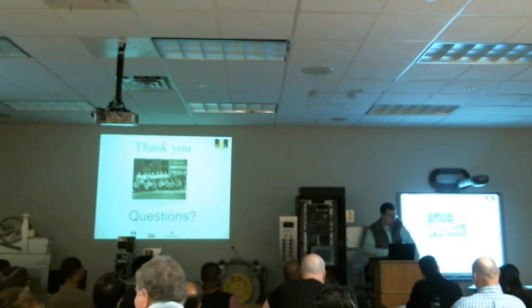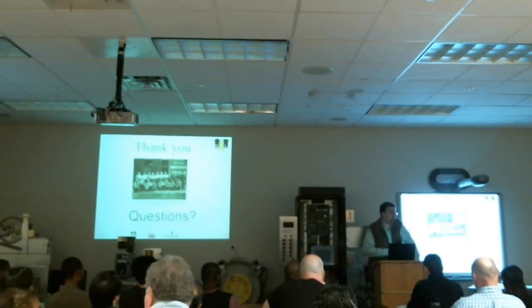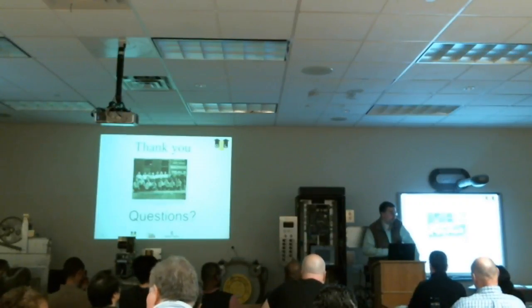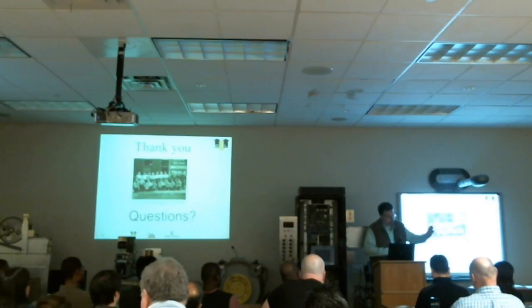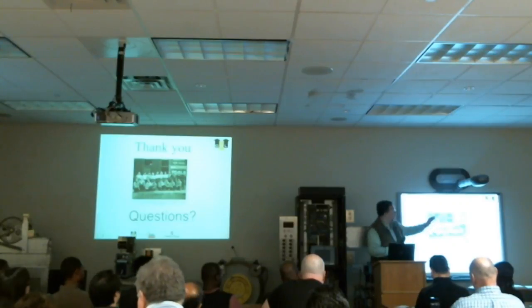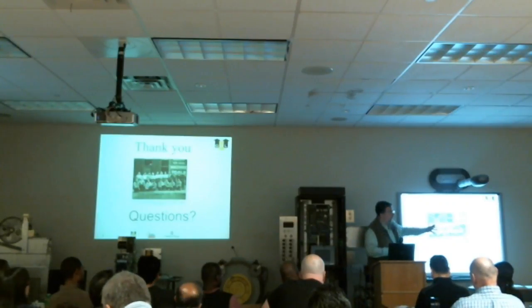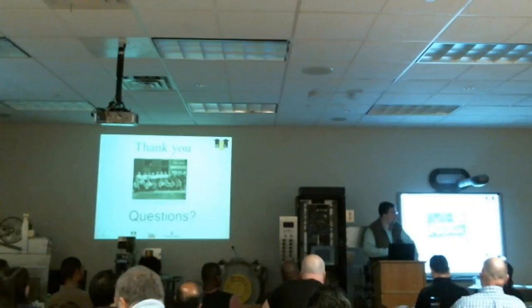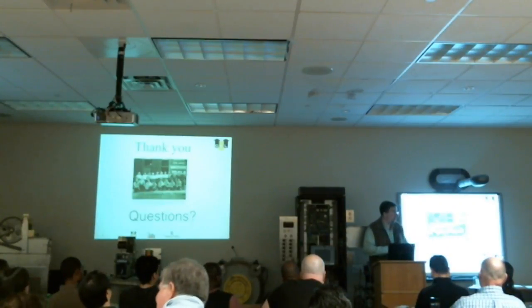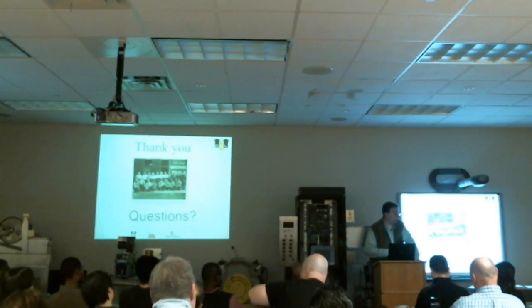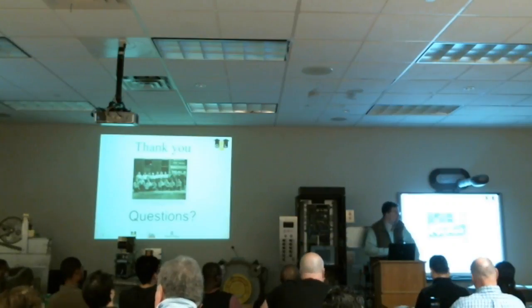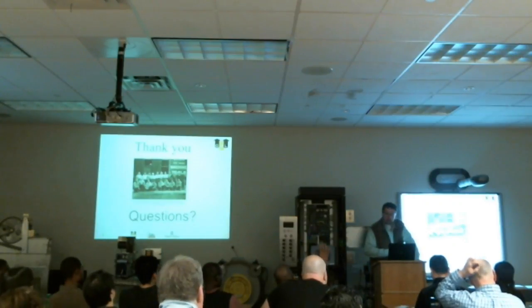Like Rick was saying, for GL product, they don't have to be stamped by a PE or a registered architect. One of the requirements is that any alterations done on a controller, not by the original equipment manufacturer, have to be modified and stamped. So any relay logic or PLC GL, we don't have to worry about that, just modifying the prints, which we still have to provide. We would mark them up and send them to the customer.